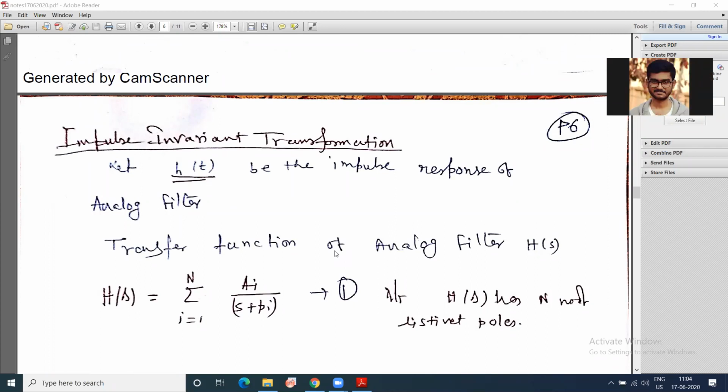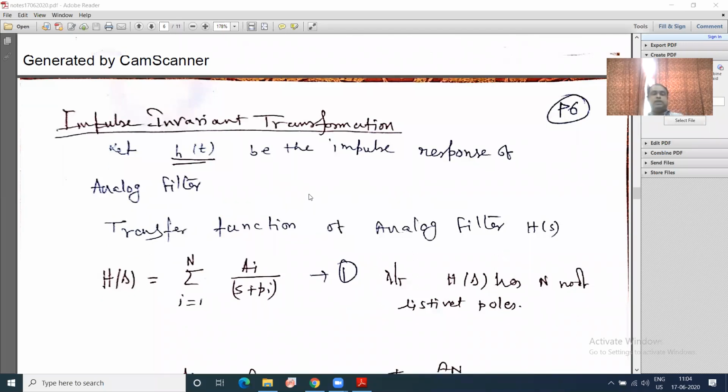Good morning, sir. So last class, where we stopped, we discussed the stability criteria in time domain as well as in transform domain. In case of a continuous time system, we investigated the stability problem in time domain as well as in S domain. There we have seen that in order to have a stable system in the S domain, poles have to lie in the left of the S plane. That is the S domain stability condition.